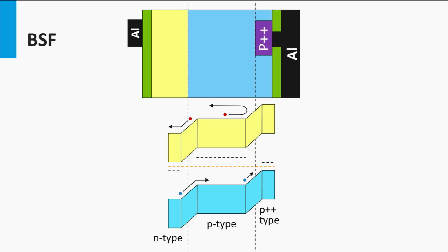In this case, it will act as a barrier for the light-excited minority electrons in the lower doped region to diffuse to the back surface. The space-charge field behaves like a passivation of the defects at the back contact interface and allows higher levels for the electron minority density in the p-doped bulk.